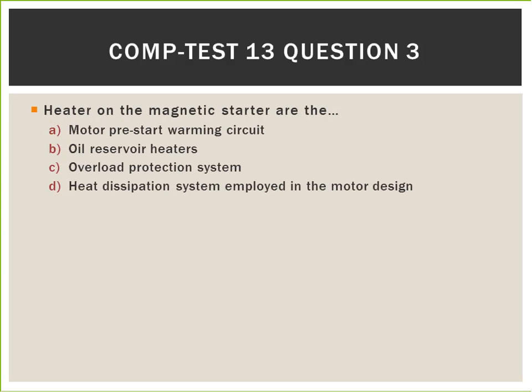Comp Test 13, question number 3. Heaters on the magnetic starter are the: A, motor pre-start warming circuit, B, oil reservoir heaters, C, overload protection system, or D, heat dissipation system employed in the motor design.